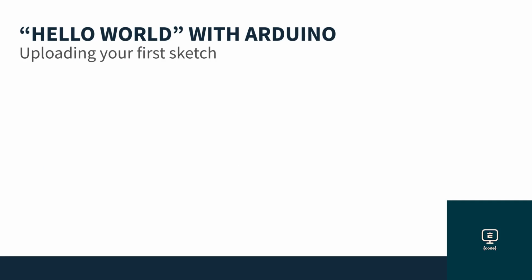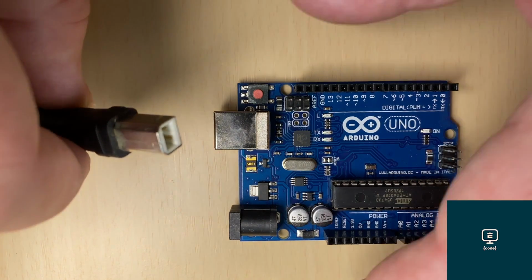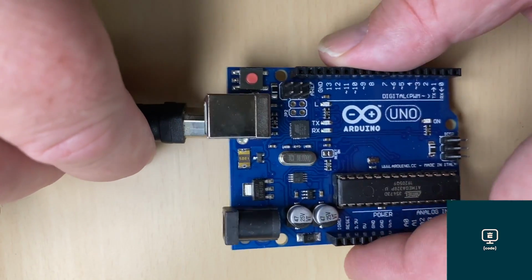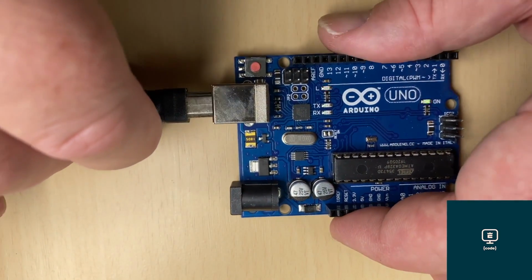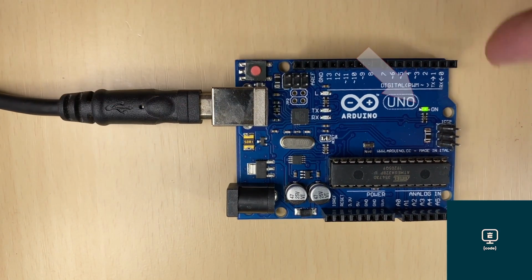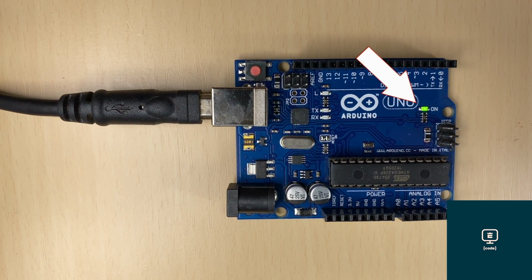So to upload your first sketch, the first step is to connect the Arduino to your PC using a USB cable. Connect the A side of the USB cable to the back of your PC. Then the B side connects into the Arduino board, and on the board you should see, along with a couple other flashing LEDs, the green ON LED light up, indicating that you're properly connected.